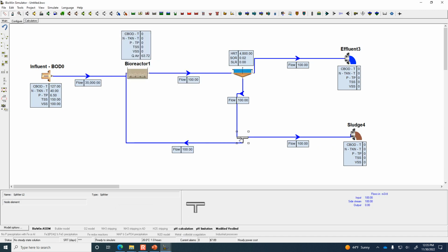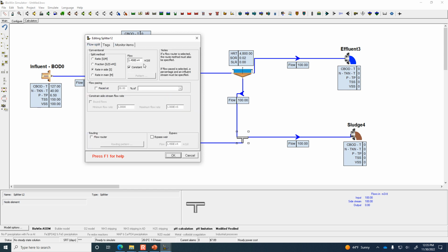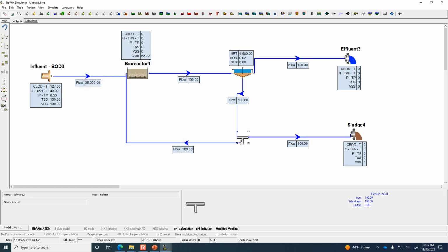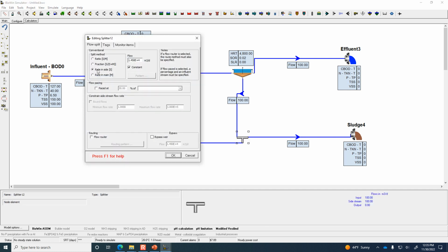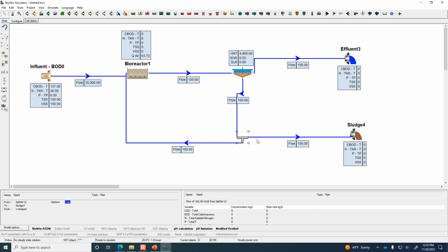So here in the splitter, the flow splits 14,500 for side, if you've got the recirculated part going out of the bottom of it. I think that this is the side and this is the main. See how it's got options for both rate in side, rate in main? So if we've got 15,000 coming in, then there's going to be 500 going out and 14,500.